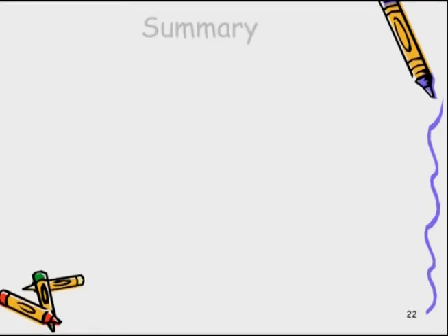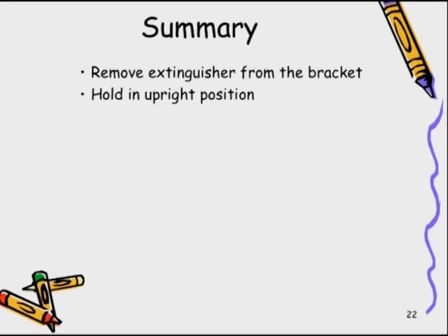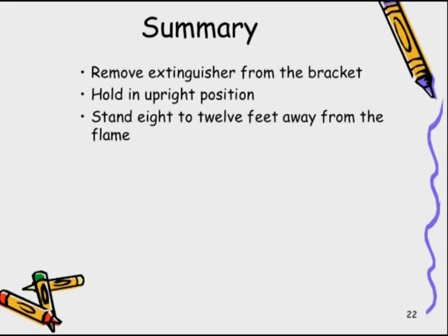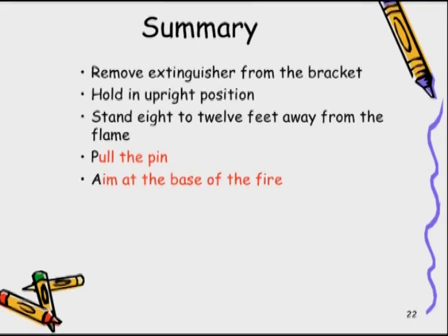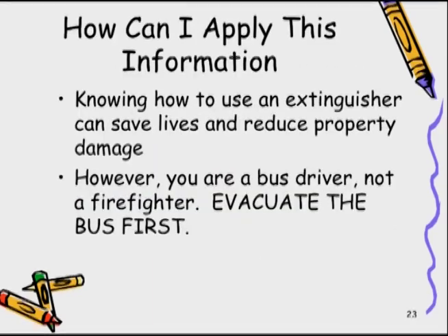As a summary, I am optimistic that you have learned some basic information from our presentation that will assist you if you ever face a fire situation on your bus. How can you apply this information? Knowing how to properly use a fire extinguisher can save lives and reduce property damage. However, you are a bus driver, not a firefighter. Evacuate the bus first. If you have any doubt about being able to safely fight the fire, get away from it and let it burn.